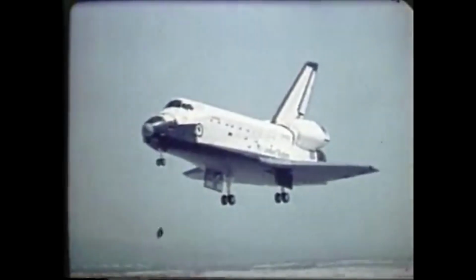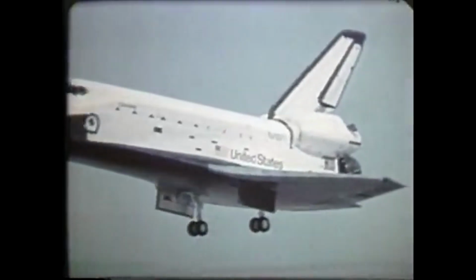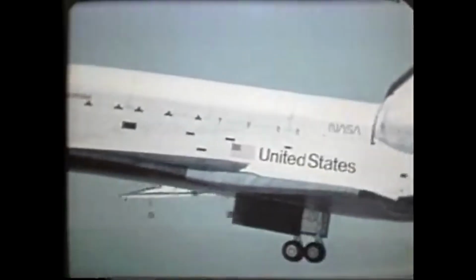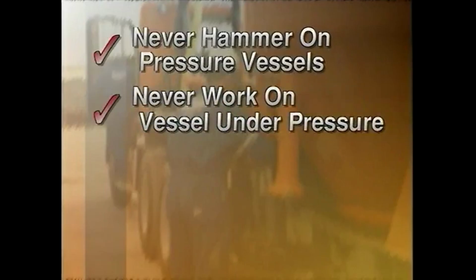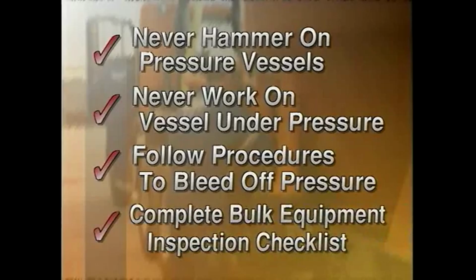We witness incredible feats performed by air pressure on a daily basis. But don't let yourself be endangered by complacency. Respect the power that even low pressure contains. Never hammer on vessels. Never work on a vessel under pressure. Follow procedures for bleeding off pressure and complete the bulk equipment inspection checklist before using any third-party equipment.